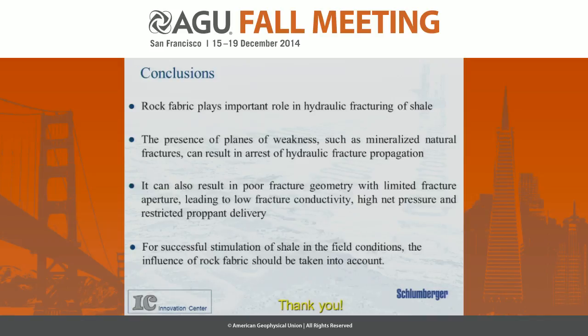Yeah, we performed many tests with the proppants, and we definitely saw that high viscosity fluid allows us to create wider opening of hydraulic fracture. And with the high viscosity fluid, we were able to deliver proppants to the hydraulic fracture. I can mention the values, for example, high viscosity fluid can give us opening of 800 microns, and in case of water injection, we had only less than 100 microns opening.